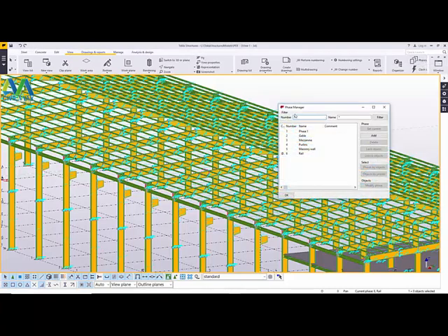Inside face manager, we have filters on particular components or parts that you've picked and categorized in faces. So we managed to group some in gables, some in mezzanines, some in purlins, some in masonry wall. Masonry wall is just about to come, and some in rail. Now we want to disable or hide the gables. I'll come to gables here and click on the button labeled objects by faces. I'll click on that and give it some time to highlight all the filters.